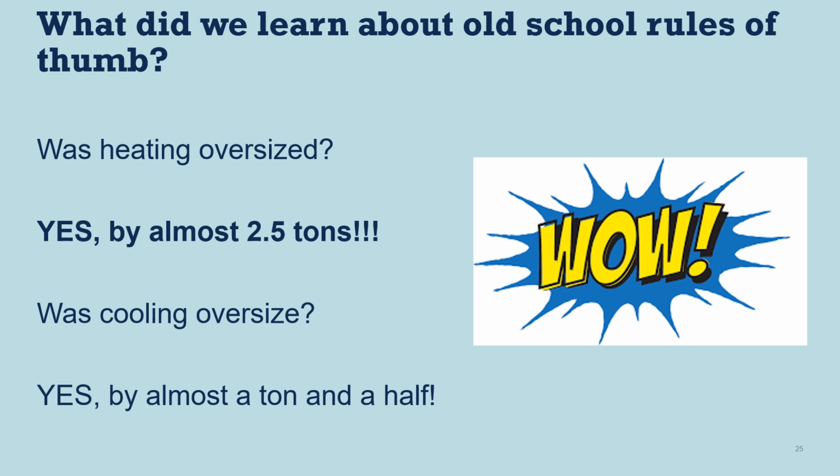So that is unfortunately what we see happening a lot in our industry. People are either using an improper tool like that load calculation online calculator, or they're just sizing off of existing equipment, and we end up with systems that are not just 1 ton bigger. They're 1.5 tons to 2.5. I've even seen some that are 3 tons too large because the tools that were being used were quite inaccurate. And that is enough to show your energy penalties, the fan energy penalty, and all those other challenges with filtration and noise and humidification all become challenging when systems are this much oversized.